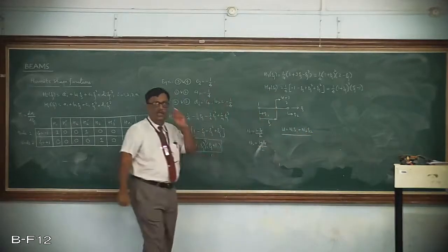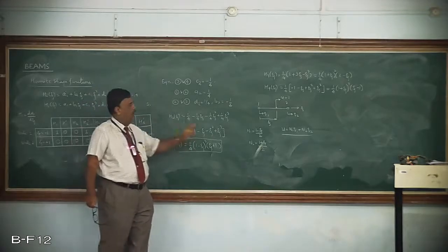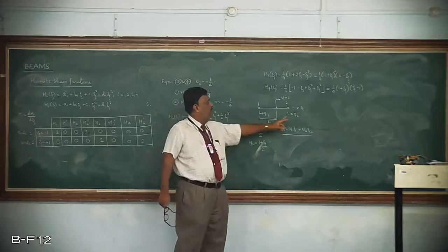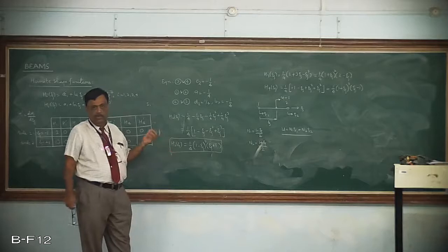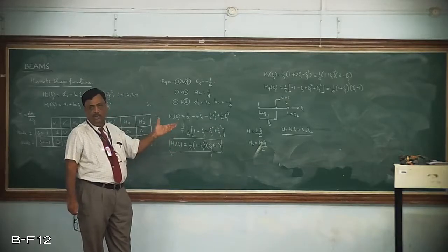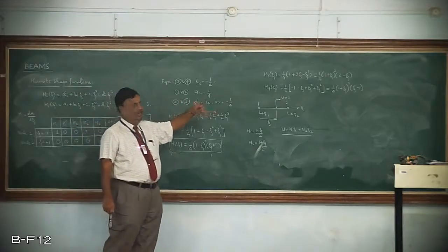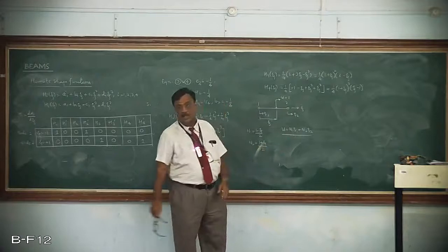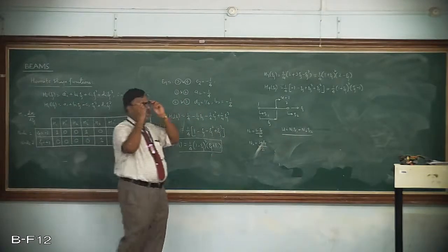To find out the unknown displacement at any point, you specify zeta from minus 1 to plus 1, you take any value. It may be minus 0.8, minus 0.3 or something like that, or beyond 0, that is 0.1, 0.25, 0.7, up to plus 1. You can put any value of zeta. By using this relation, I could have found out the displacement at a given point.